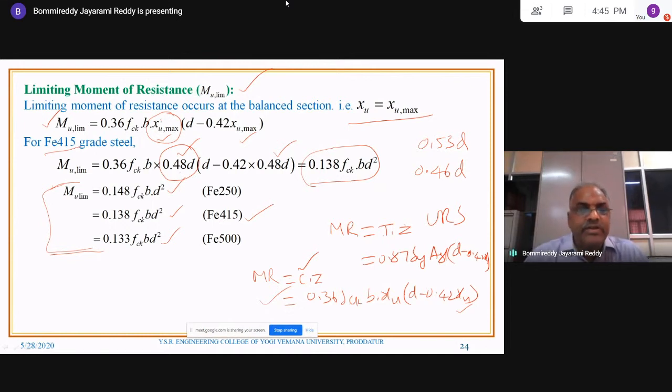The case is different in working stress. In the working stress method of design, as the steel reinforcement is more and more, and till the concrete is able to take the load, the moment of resistance is continuously increasing. Whereas in this case, once the steel reinforcement reaches its limiting stage, any additional quantity of reinforcement provided gives no improvement in the moment carrying capacity of the section.